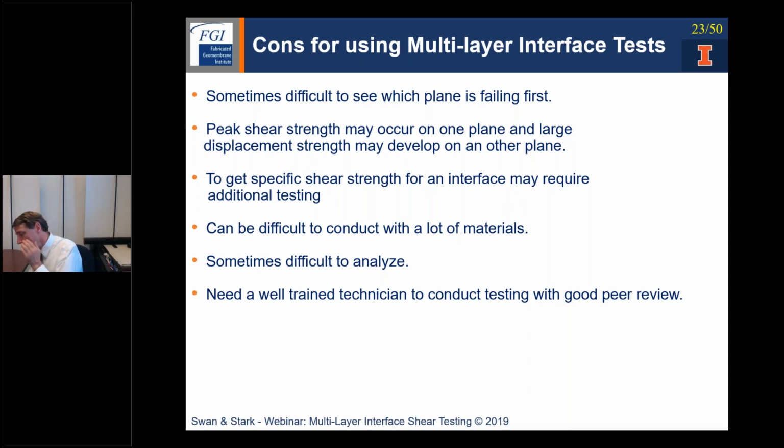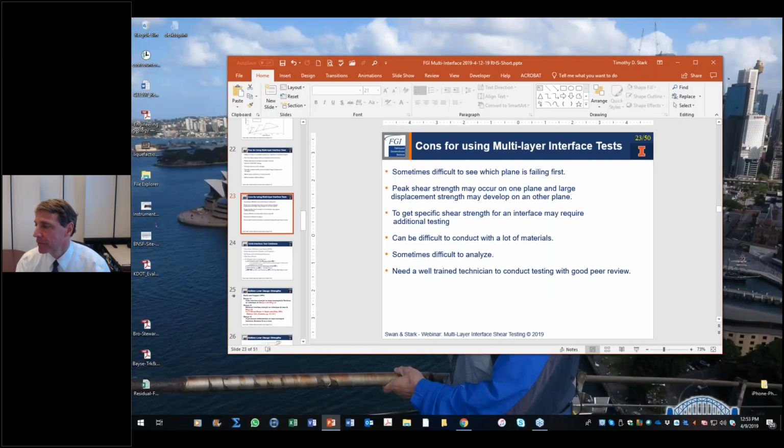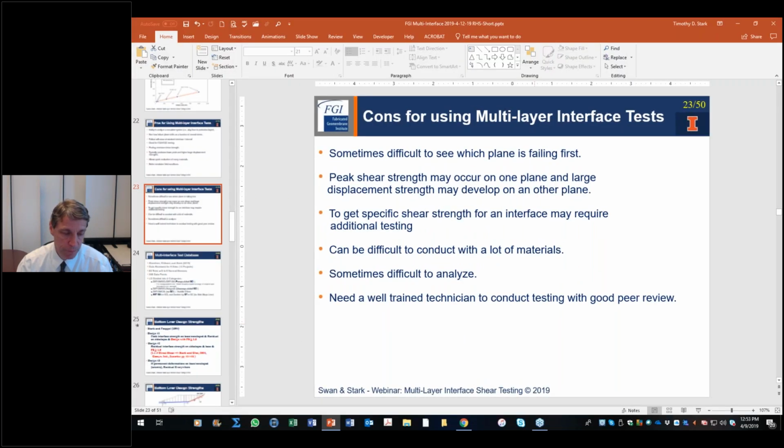In-house tensiometer? Yeah, and I guess if you're trying to do some laboratory conformance testing, I would suggest that you do an 8-inch wide, a wide width specimen, using like a Curtis grip or some kind of grip where you can grab both the geotextile and the geonet. I believe there's an ASTM standard for that test. I don't know. Okay. Great.